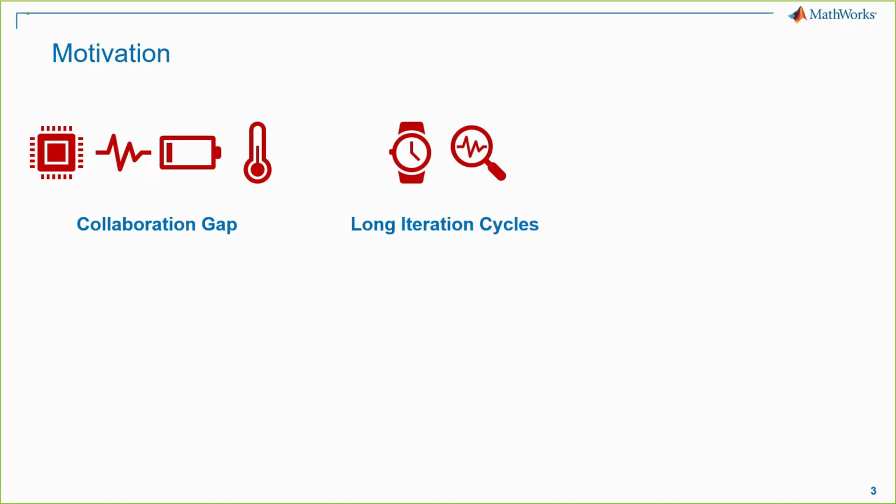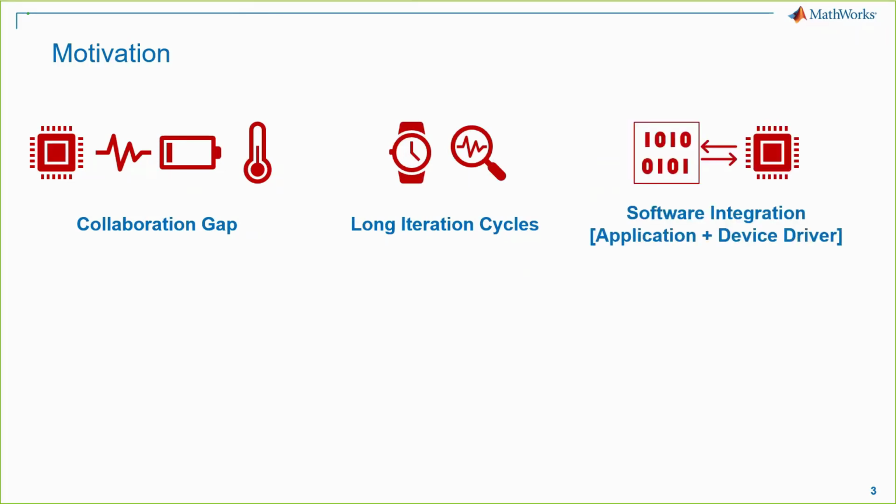Now let me mention another challenge that led to this webinar. It's about the software integration between the device driver code and application layer code. As Marius showed earlier in the demo, BMS application software can be designed and verified independent of the hardware using Simulink. However, we need to interface inputs and outputs of the application layer code to device driver code. For example, reading battery cell voltages and temperature values from cell controllers.